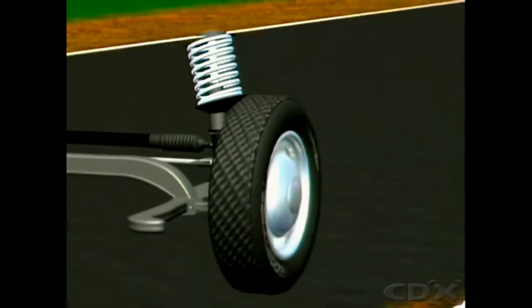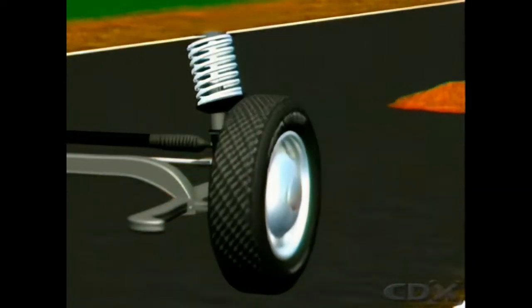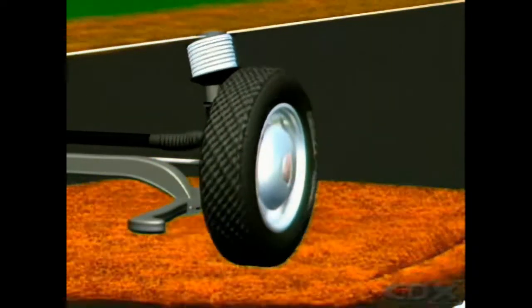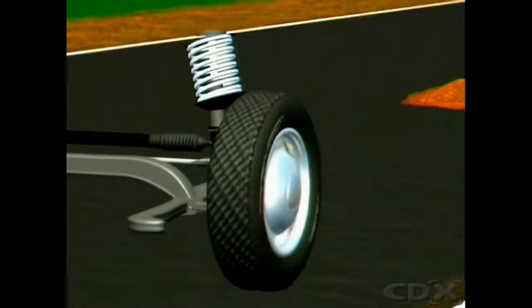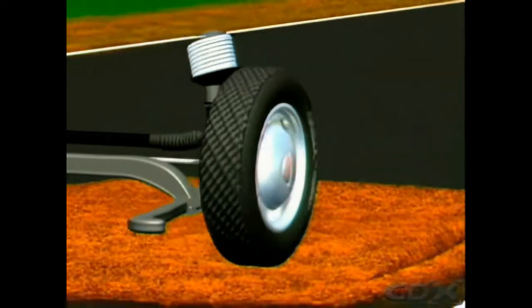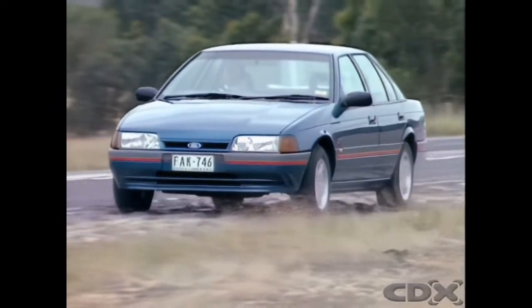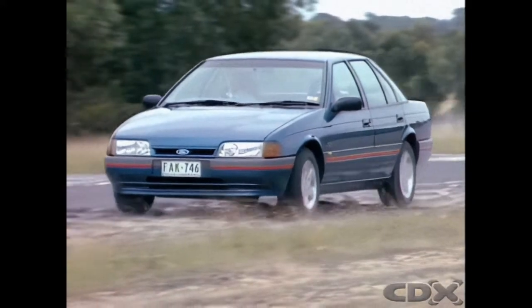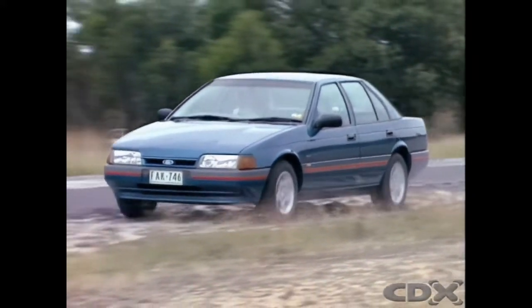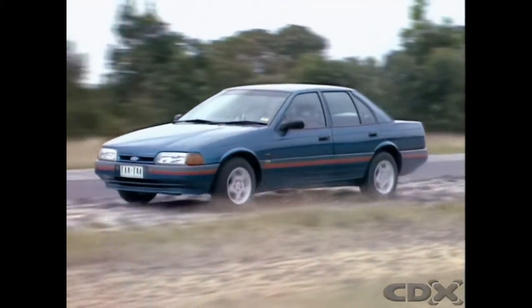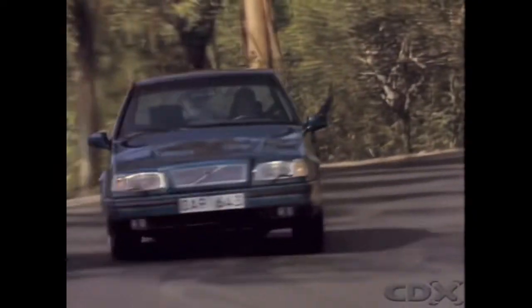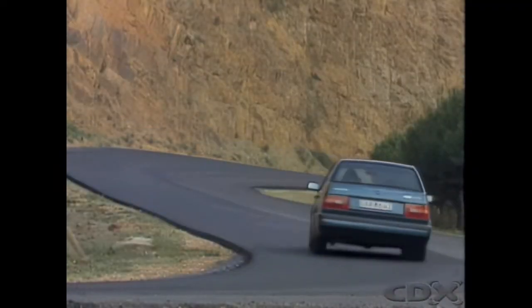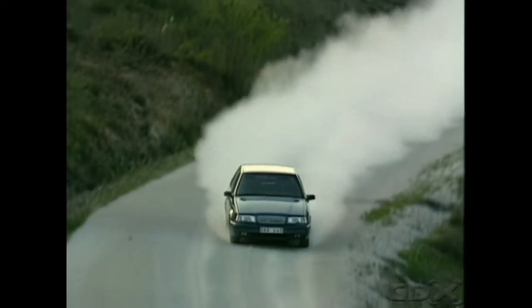When large and heavy wheel assemblies encounter a bump or pothole, they experience a larger reaction force, sometimes large enough to make the tire lose contact with the road surface. Wheel and brake units that are small and light follow road contours without a large effect on the rest of the vehicle. At the same time, a suspension system must be strong enough to withstand loads imposed by vehicle mass during cornering, accelerating, braking, and uneven road surfaces.